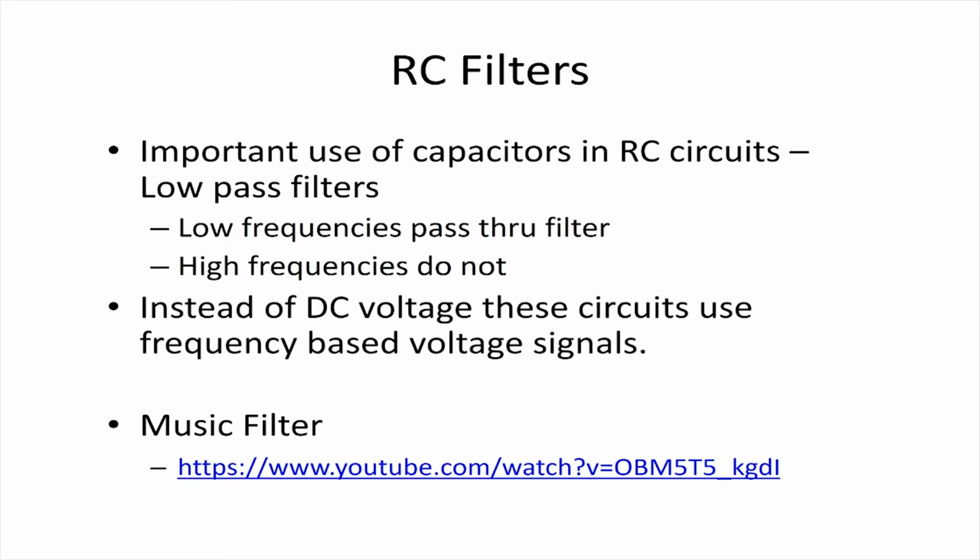All right, one final application that we'll look at from a capacitive perspective is, for all of you who are music fans, RC filters, which are an extremely important way to clean up the music signal and to decide what passes through each of the channels. So if you have a low pass filter, and they'll be called either high pass or low pass or other descriptions for these filters, in a low pass filter the low signals are passed through, but it blocks the high frequency signals. And that's the intention of a low pass filter.